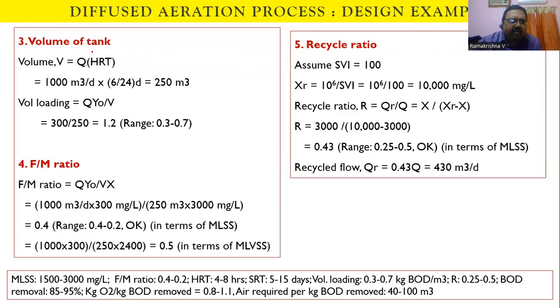Now, talking about the volume of the tank, how do we calculate it here? The discharge is equal to volume by time, we know that. So the volume will be equal to discharge multiplied by time. Q is the discharge and HRT is the time, which you have taken as 6 hours. Multiply that, and you have 250 meter cube.